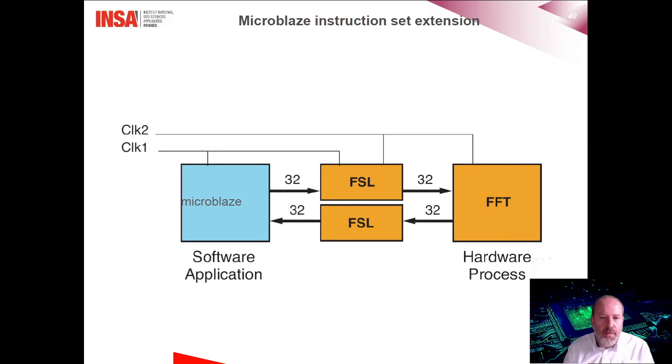You can modify the instruction set of the processor to integrate this FFT as an instruction that can be directly called from software. This is very powerful because it's completely transparent to the final users. You can simply call a specific instruction in your program to perform a complex computation without considering very complex design steps and without considering the way the MicroBlaze and the IP, the FFT, are communicating.